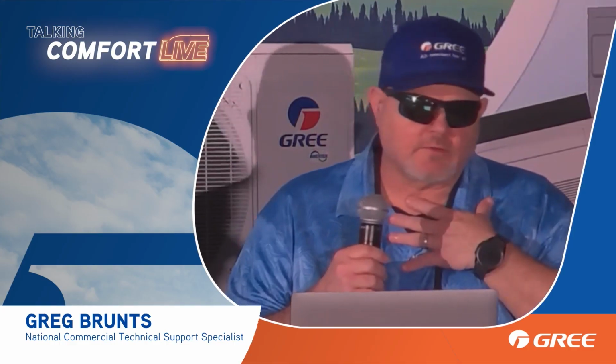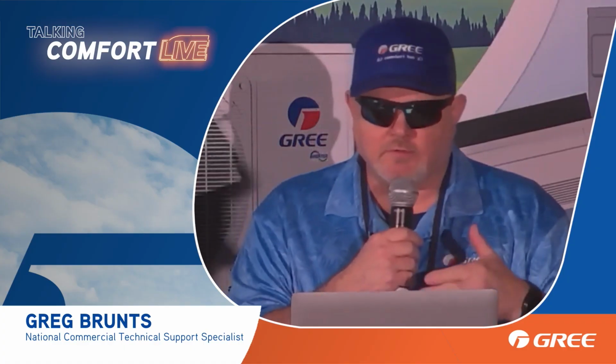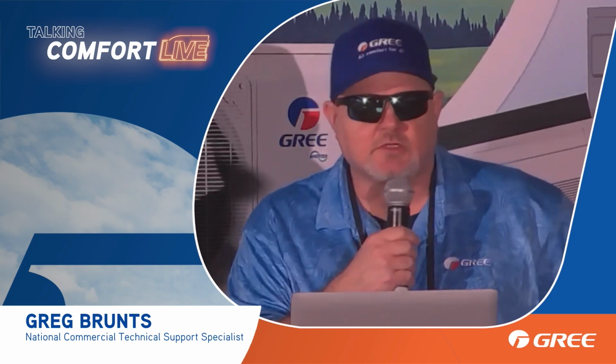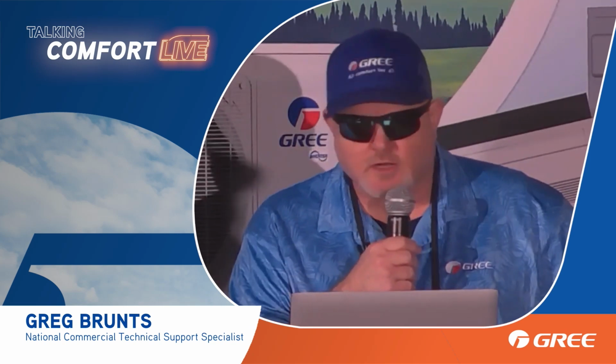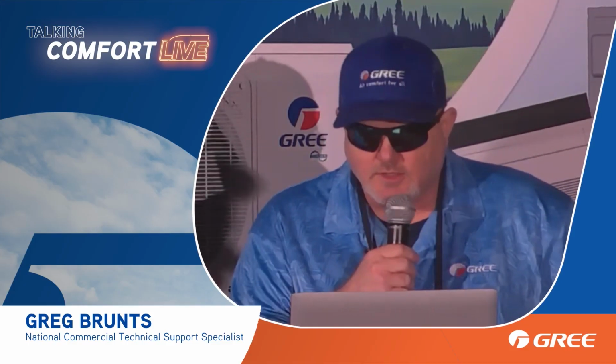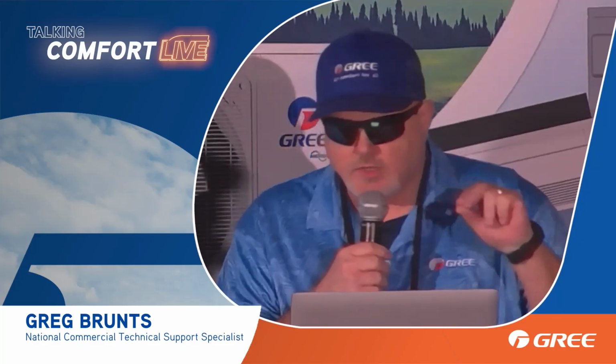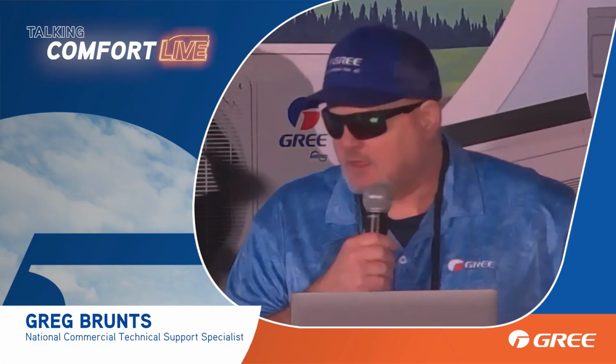So, for guys like myself that don't have a doctorate like Dr. Justin, with all of the fancy technologies, their names, it's air fuel mixture. You're not going to have the right air fuel mixture inside that compressor, inside that system, to actually give you a flammability or explosion or anything like that. The chances of you having that right air fuel mixture inside that refrigeration circuit is slim to none. The chances of you having that right air fuel mixture in somebody's home is next to none.